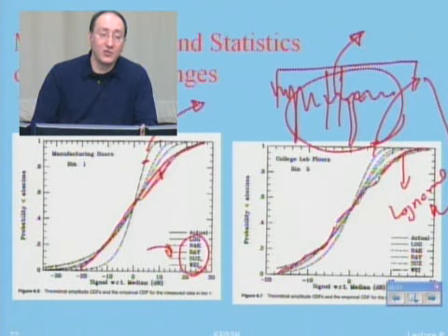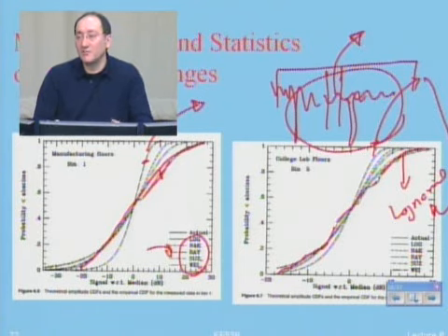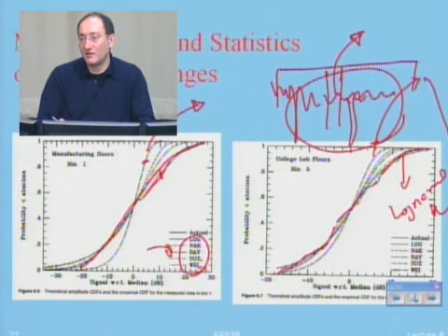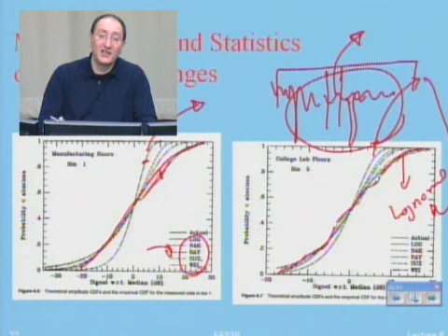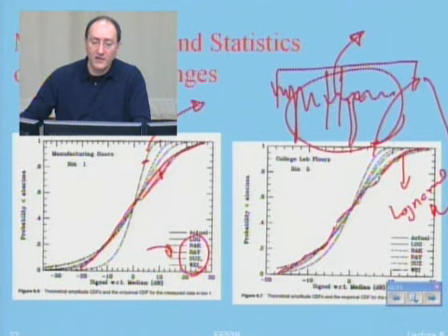Because the models for ultra-wideband, all of them, assume that each path is log normal. And arrivals are not Poisson, either delta-K or modified Poisson, or they have other solutions for that. So this is one point.